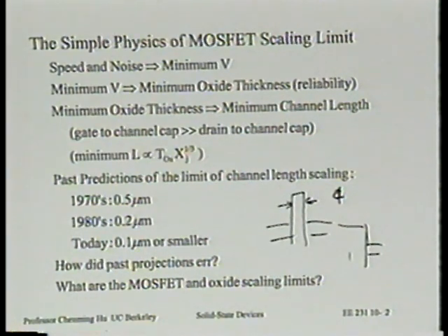From TEM pictures, by the way, and you probably know this better than I do, you can certainly see an extremely sharp transition, right? Which I know does not necessarily mean you immediately go into a good amorphous SiO2. But the electrical property of this SiO2 is extremely good. If you look in the literature 10 years back, a lot of literature just assumed there's an interfacial transition layer, that anything is fair game to assume about that. But today, we actually assume the opposite. That is, we assume everything is unchanged in this very thin oxide compared to their thicker counterparts.